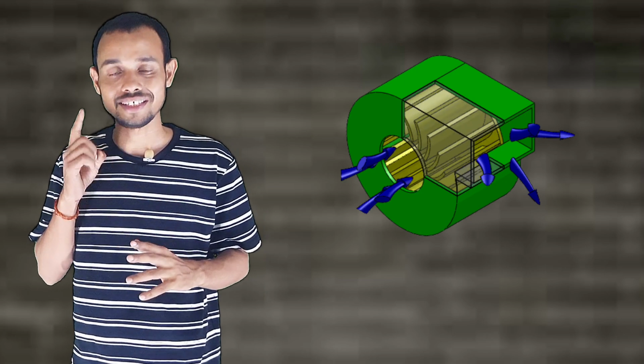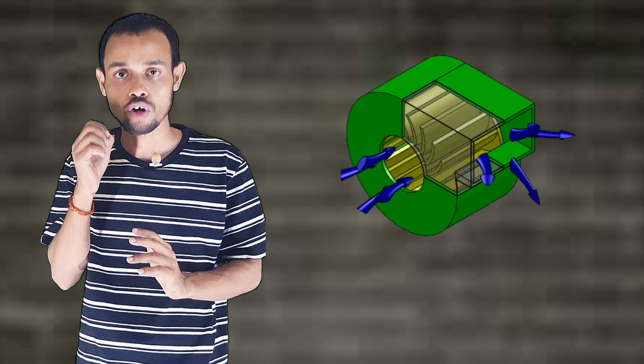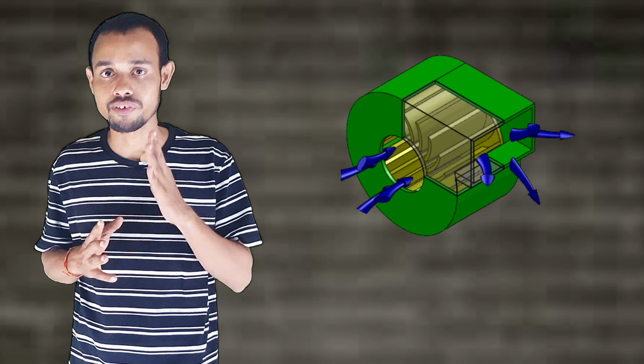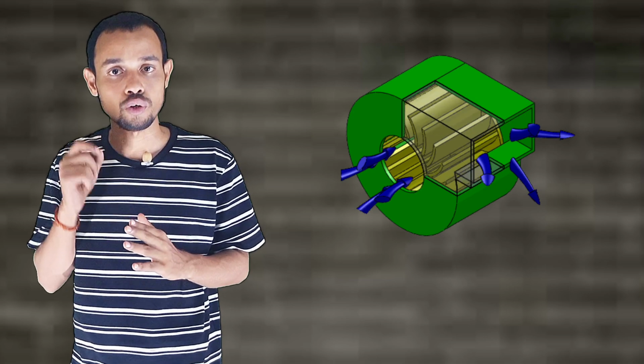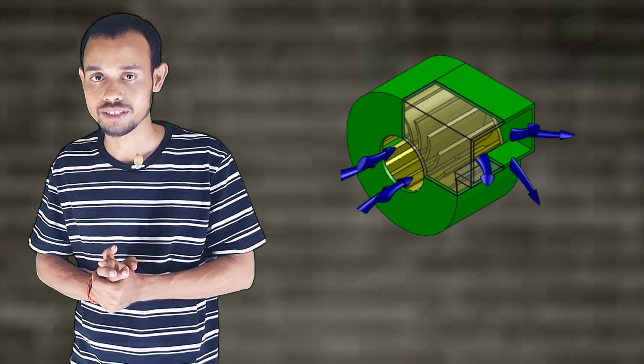So first is centrifugal fan. What is centrifugal fan? A centrifugal fan throws air out at a 90-degree angle, used in the high pressure applications, perfect for the air movements through the ducts, energy efficient and low noise design, used in AHU, exhaust system and the clean rooms.